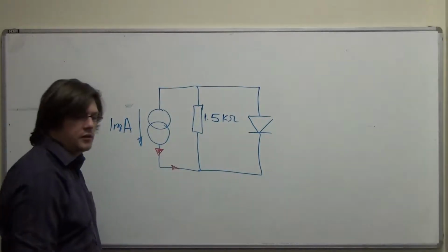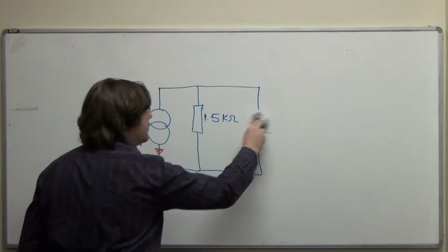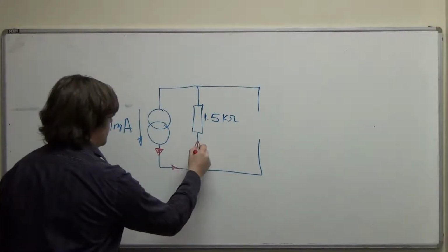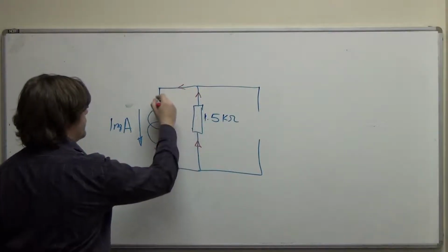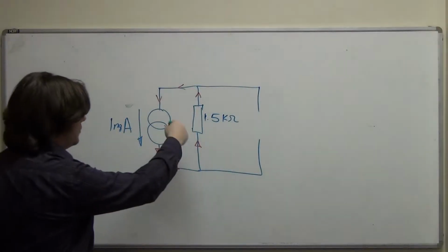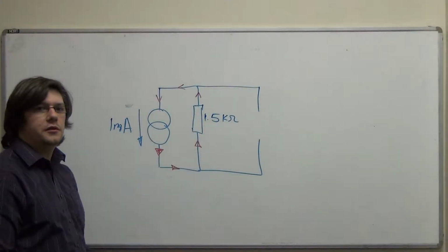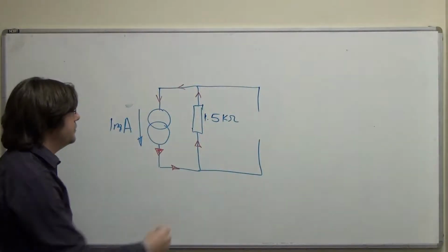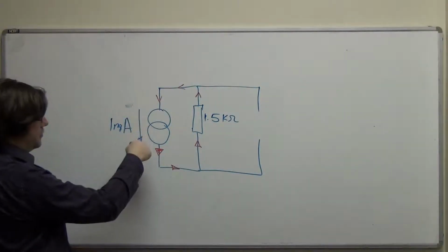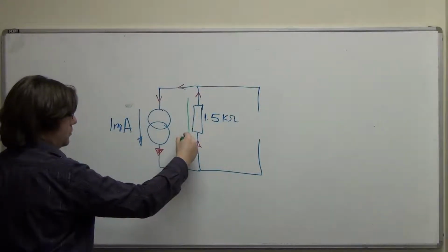and we'll worry about the resistor and the current source. So, no diode. Current goes up there, down there again. In that case, because the resistor dissipates power, the current and voltage must be in opposite directions to each other. It's in lecture 1 or lecture 2. So I know, having drawn the current source, how it is in the question with the current going down the page, and the current goes round this loop, that I must draw the voltage this way.